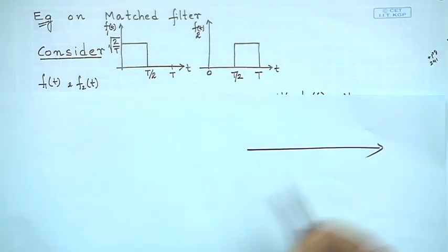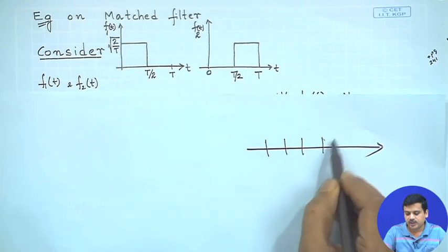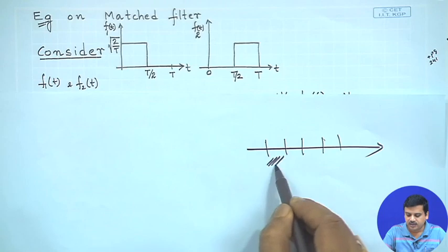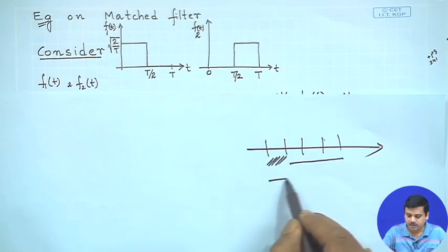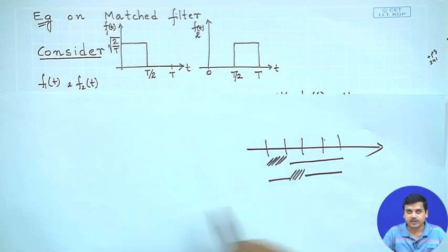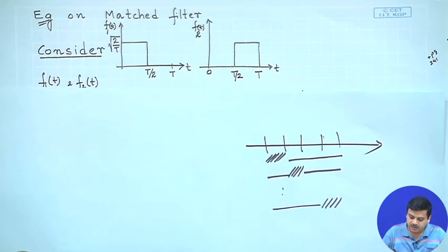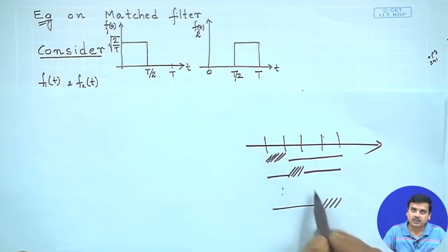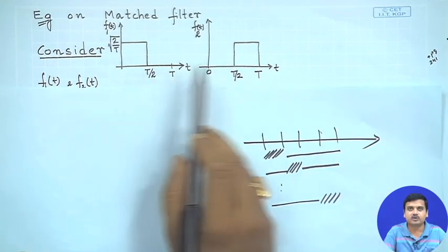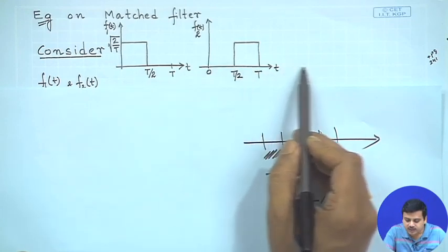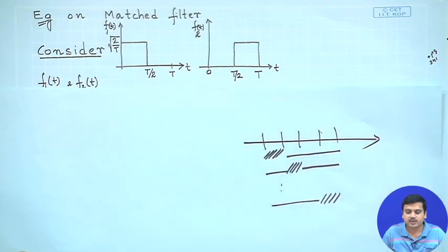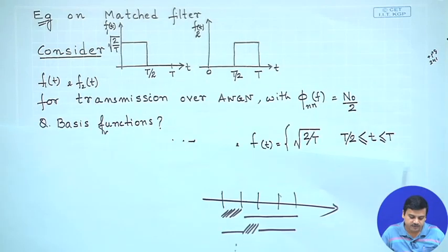If you are very careful, you will note that we discussed n dimensional signaling. When we discussed n dimensional signaling, we said that a certain duration of time could be divided into time slots, and you could send a signal in one of the time slots and not send anything in the others. In that case these signals are orthogonal to each other and you have n signals. Here we have two signals which are orthogonal to each other, created in the time domain. You could in this fashion create a longer duration of time, divide it, and create n orthogonal signals. So, this is in the baseband form.